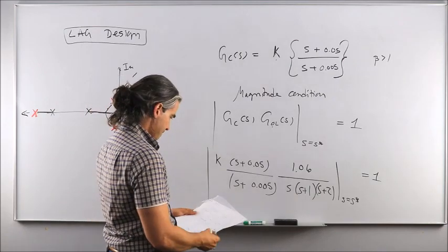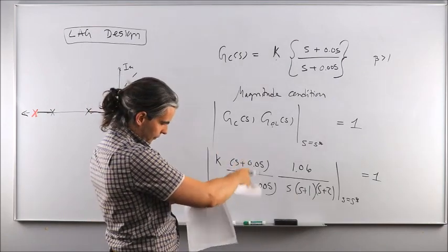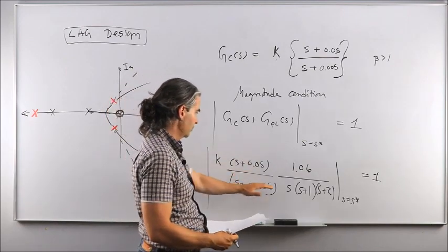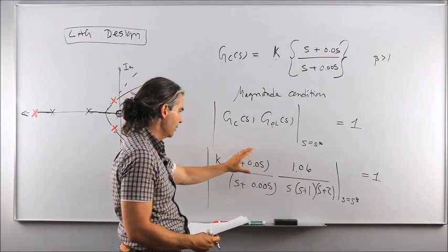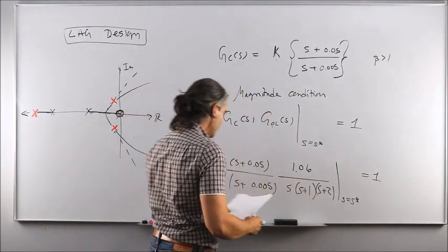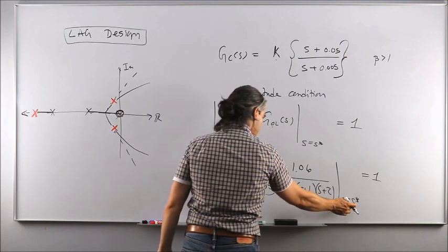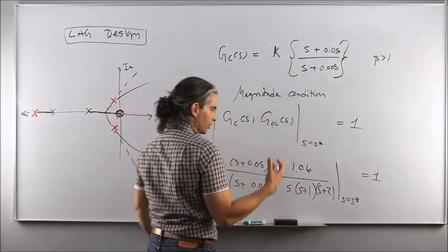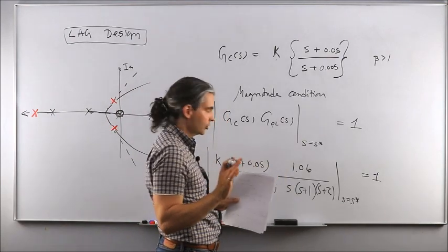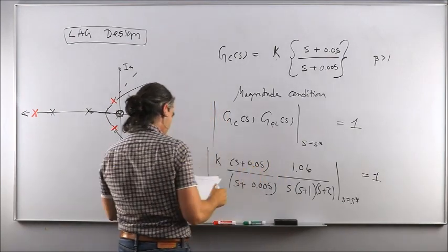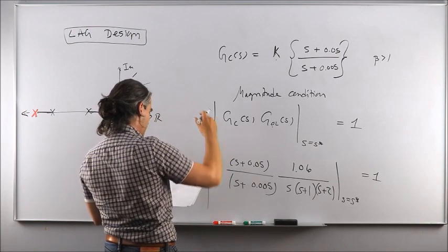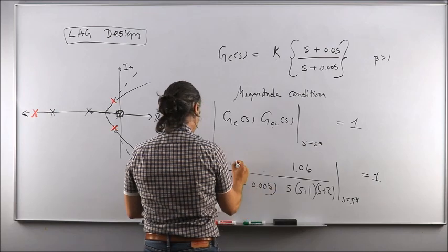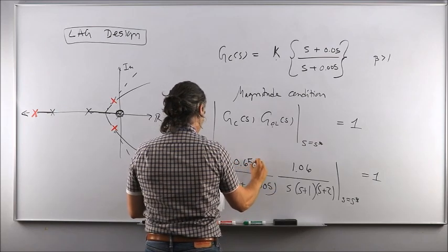Okay. Let me just give you the distance of all the individual poles and that single 0 from s star. Okay, so the distance between s star, which is here, or s star is the same as the original closed loop pole locations because we don't want to touch them, and that 0 here, if you do the square triangle thing we did, you're going to end up with a distance of 0.653.